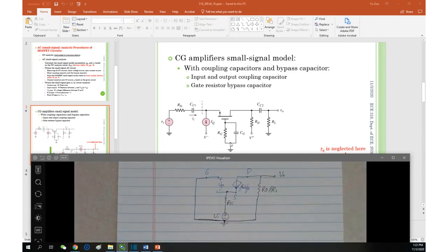Here we go. The reason is, as Daniel just mentioned, this capacitor is short, right? Remember, we treat all capacitors, no matter what, as short circuit in 318, this class at least. So if this is short, what happened? Your short path is exactly parallel with RG. What happened then? No current is going to flow through RG. RG is open circuit. Zero current. Therefore, the gate goes directly through the shorted CG to the ground.